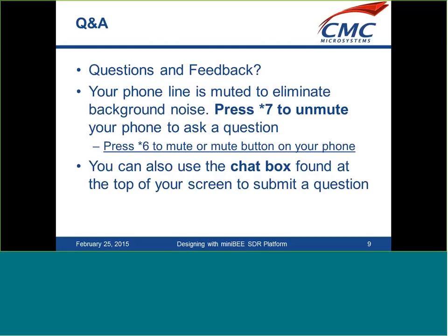If you type that minicom command, it will give you the format of the command. You can specify whether you want to set channel A's local frequency or channel B's local frequency, so they can be set independently from each other.